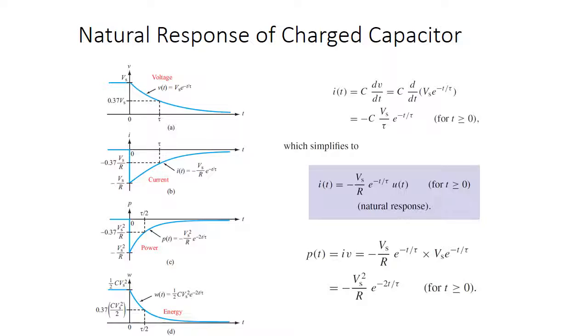Interestingly, we're going to look at then just logically what happens with the current after that. If you have that same circuit before 0, at any time before you throw the switch, remember you have an open circuit there. An open circuit means you have no current flowing. No current flowing means 0. That's why you have a 0 all the way from negative infinity of time to 0. Now, immediately when you throw that switch, you're going to get a step, an impulse all the way down to your minus Vs/R. And then your current is slowly going to decrease back to 0.